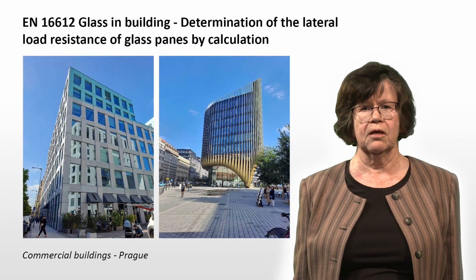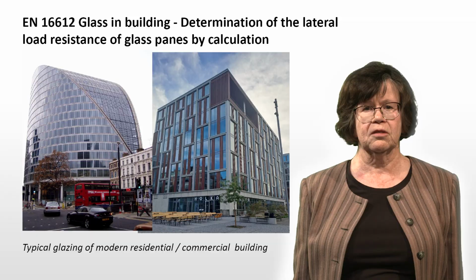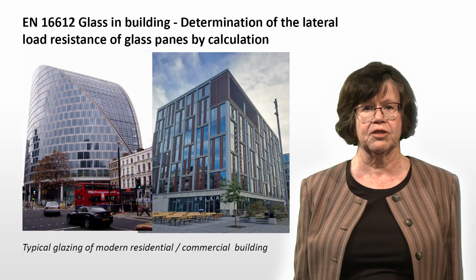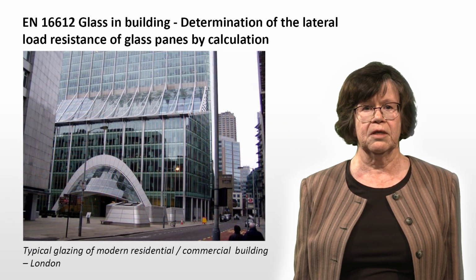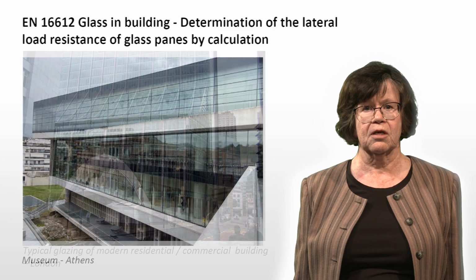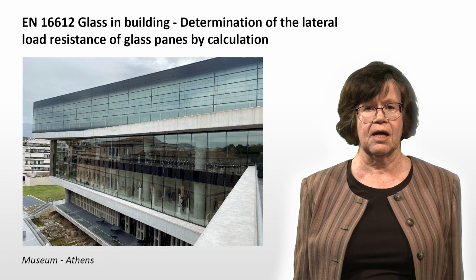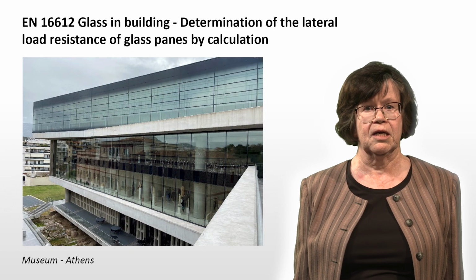The load thus mainly includes wind, thermal stress, and the load specific to the insulated glass units: temperature, altitude, atmospheric pressure. The definition of infill panels, which can be designed according to EN 16612, is usually given in the national annex. The design of structural glass elements corresponding to the class consequences CC1 and higher should follow the provisions in EN 1990.